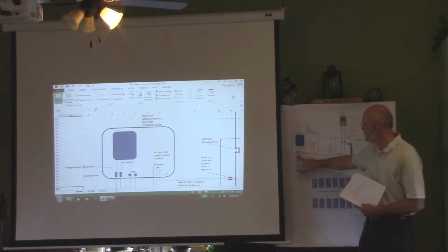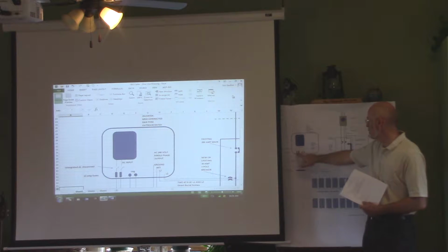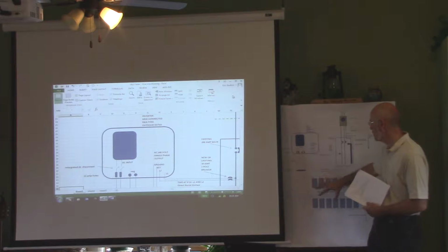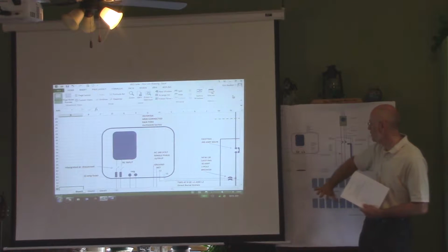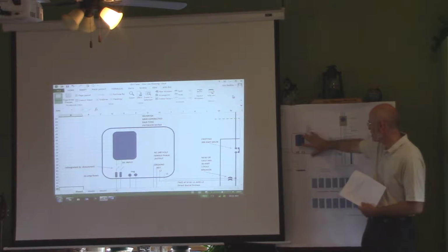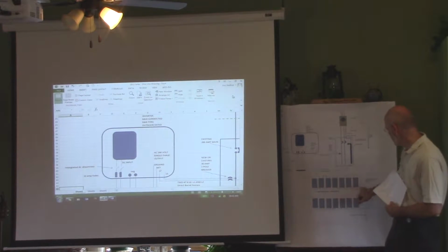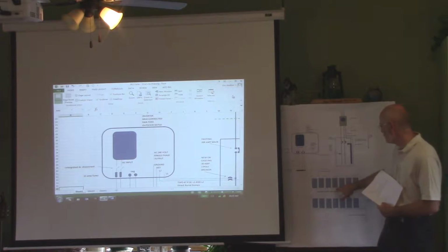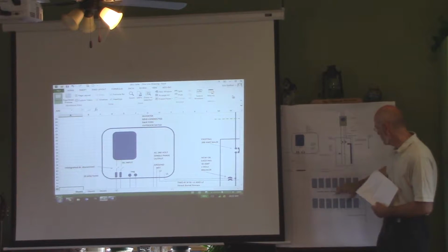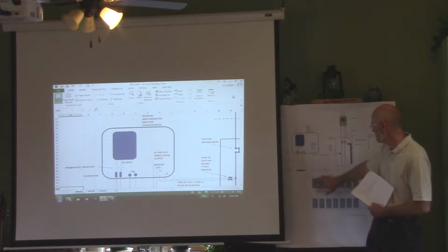So we got the DC, the direct current side, sort of completed. Now, there's fuses here, and that's in case something shorts out somewhere or lightning strikes. We want these fuses to blow and protect the inverter, because this costs a couple $1,000. We don't want to wreck it. And this can be outdoors or indoors. So if lightning strikes here, you're going to see there's a ground wire, the green wire connects to a ground rod line. So the aluminum frame of these inverters, we want that to be the potential earth, because that's where lightning wants to go, to get neutralized.